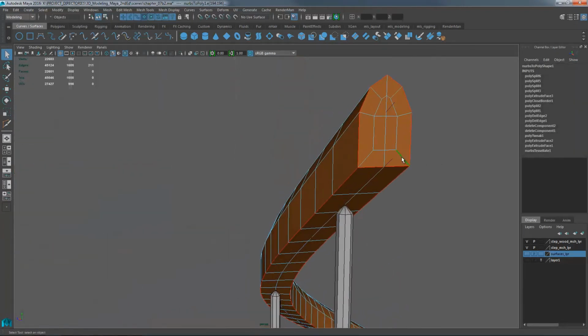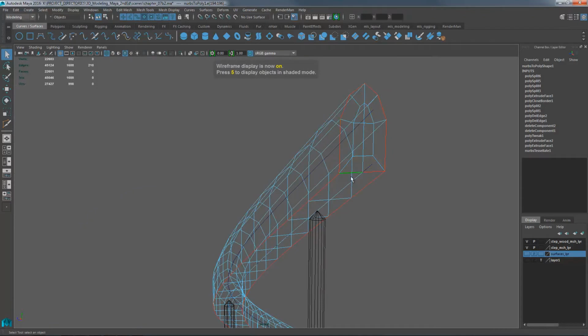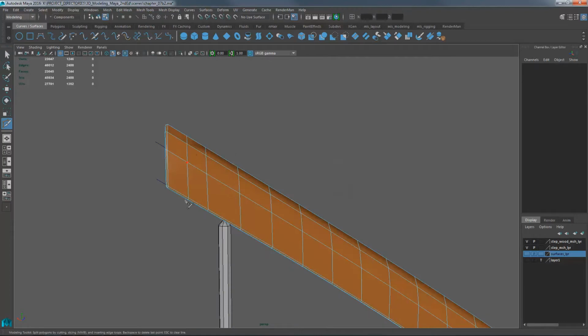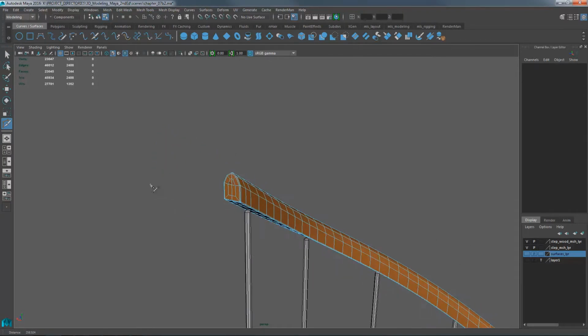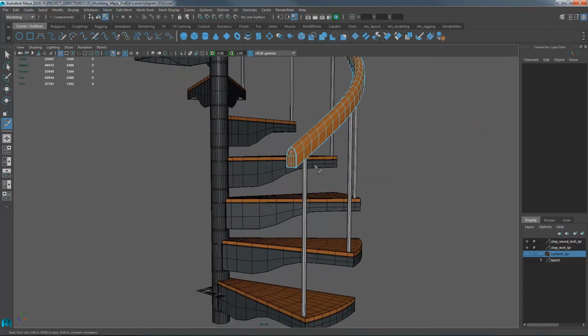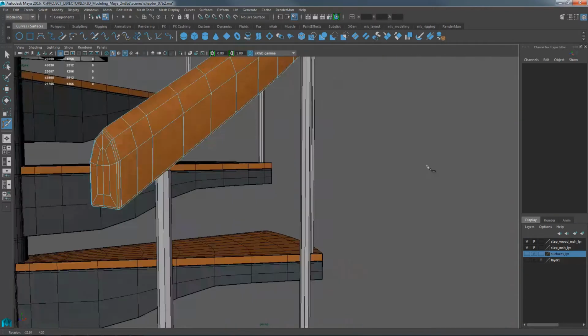I have made this selection for the bevel, where I've selected the outer edges of the ends and only the two lower edges along the bottom, and the remaining edges are ignored. And I'll run the bevel. I'll add one more supporting edge loop up here at the top using multicut without edge flow, just to help even out the spacing. Just that top end there was a little weird. And you might want one down here too.